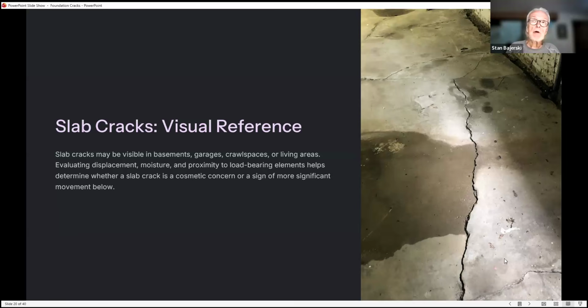It's not structural for the most part because these slabs are up against the footings of the garage, but it is a nuisance. About six months ago, I had one that was off by like 2-3 inches. I told the guy this slab's got to be destroyed and taken out, you've got to compact the ground again, keep the water away from it and put a new slab in, unless you want to take a trip through the Rocky Mountains here. That's the way it looked. So that was a pretty big job, even though it wasn't a structural issue.